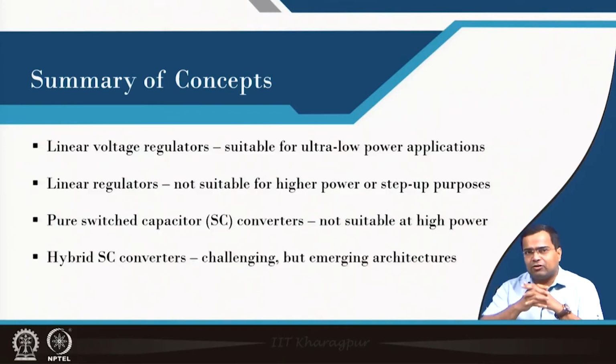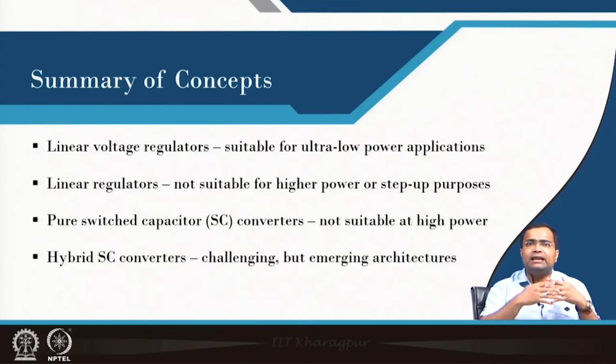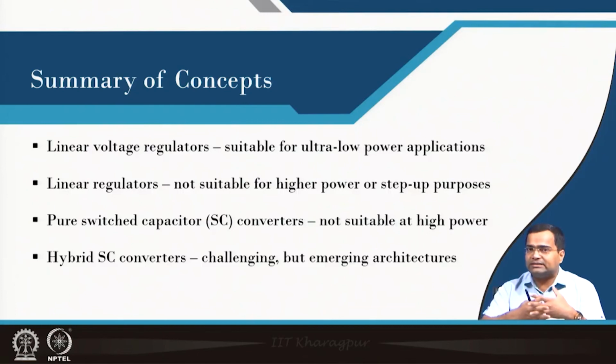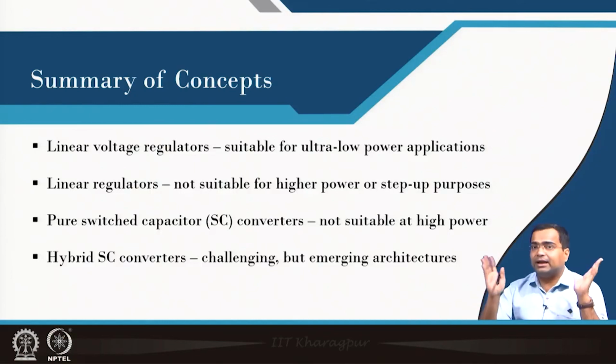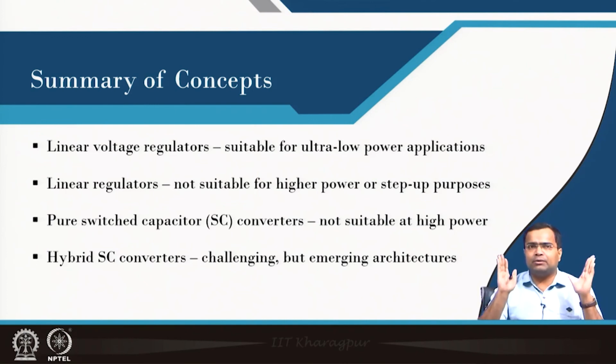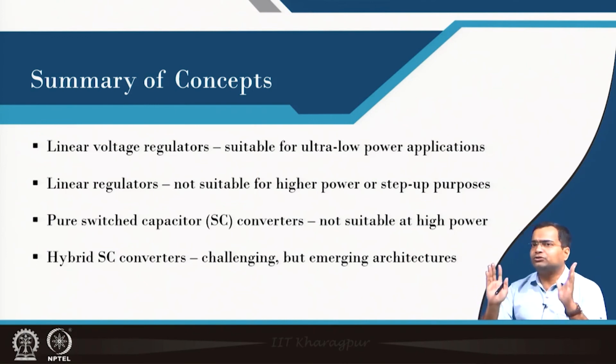And the hybrid switch capacitor converter, where along with the flying capacitor we consider a smaller inductance, is gaining a lot of attention nowadays for high frequency, high power density switch mode power converters, where we can design a much smaller power supply using a hybrid switch capacitor architecture, and this is an emerging area of research. But still there are a lot of aspects like optimization, modulation, and voltage balancing that need to be addressed.